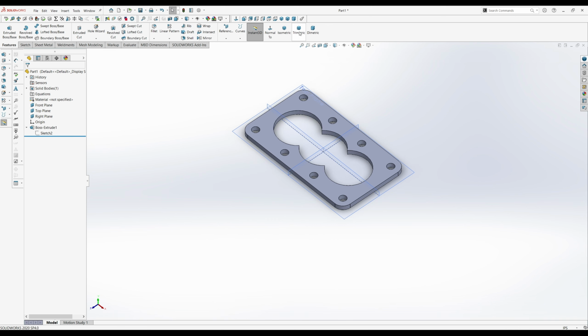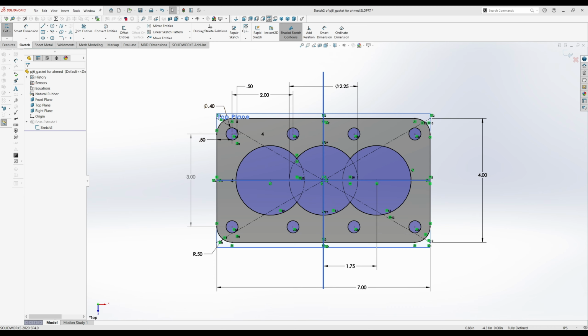So something that I made a mistake on was the patterning. There should be 4 circles going that way in the X direction, and there's only a mirror reflection of them, so there should be only 2 sets of patterns. One's in the X direction and the other's in the Y direction. So you should only have 8 holes total. What I said previously was that there was 4 in the Y direction, and that's why we had those yellow circles down here that we had to delete.